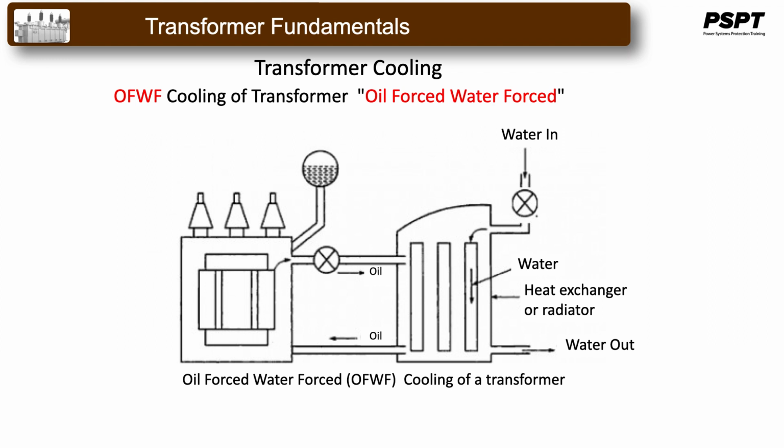In OFWF cooling systems of transformers, the hot oil is sent to an oil to water heat exchanger by means of oil pumps, and there the oil is cooled by circulating cold water on the heat exchanger oil pipes. OFWF means oil forced, water forced cooling in transformers.